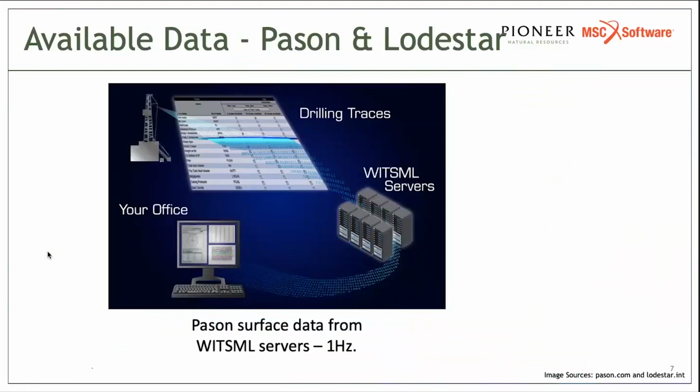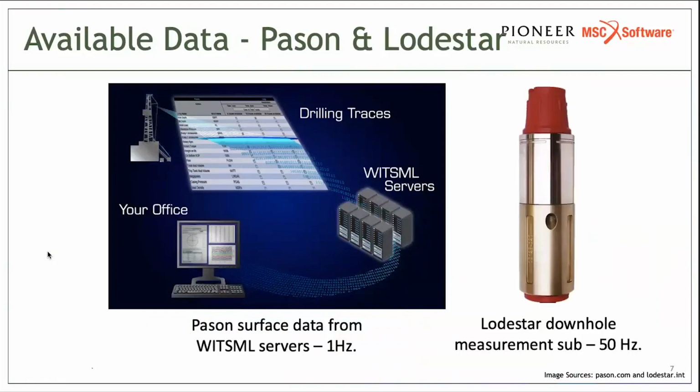And in some wells, we have recorded downhole measurements using Lodestar downhole measurement subs. We can record the vibrations, torques, and loads happening down the hole, but it's not able to send this data to the surface in real time. Data was available at a frequency of 50 Hz.